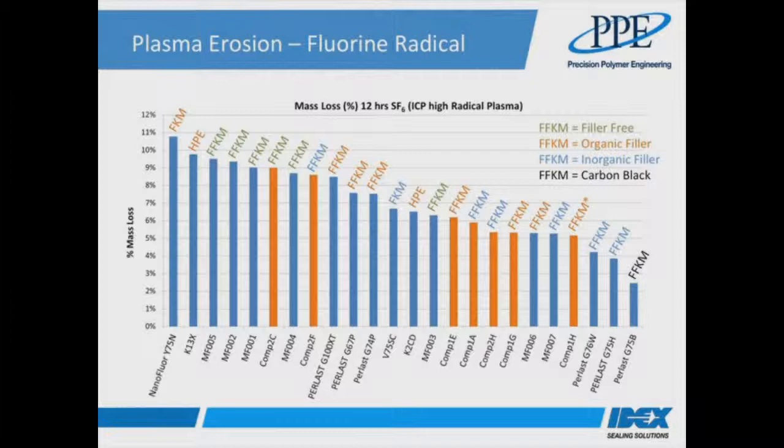Okay, so the best materials are a carbon black filled and again a couple of inorganic filled materials. Thereafter it becomes a bit blurred with some organic filled grades in the mix with inorganic filled materials. Generally the filler-free materials are again towards the high erosion rate end of the spectrum, but not this time the worst performers. But again, as we've seen previously, one of the filler-free development grades outperforms the other filler-free materials and is in the mix of medium performance grades.